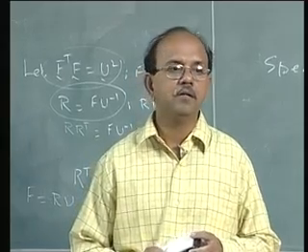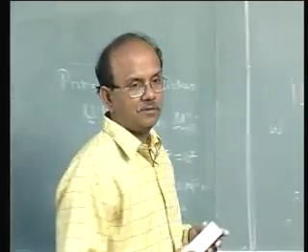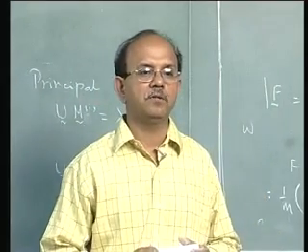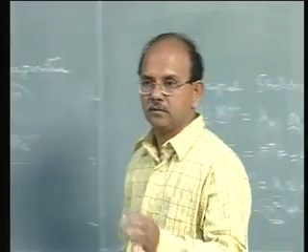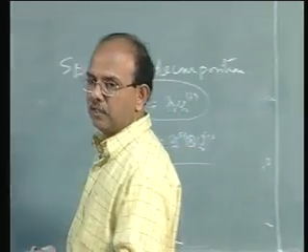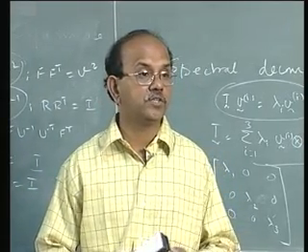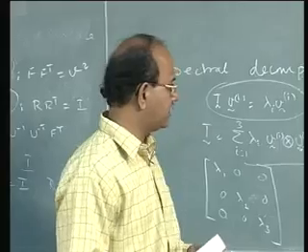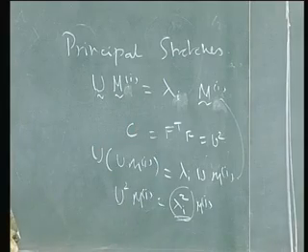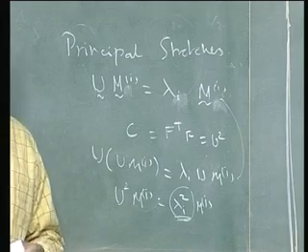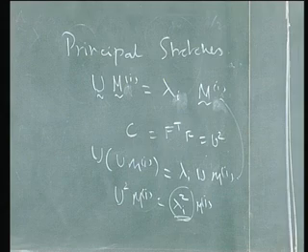That means that when you are dealing with the current or deformed coordinate system, which means the Eulerian coordinate system, then the measure that you would use is Almansi strains. So it's important that we also understand the relationship between the lambdas of U and the lambdas of V. Are they the same? Are they different? And how do the eigenvectors also get transformed?